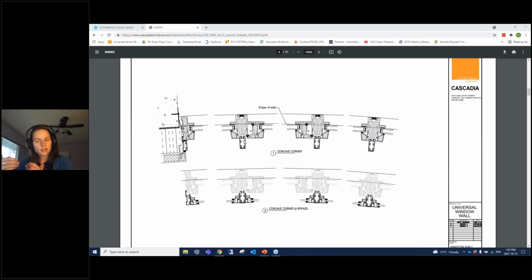There's no thermal bridge there, so to speak. So it's specifically designed to have a negligible impact on the performance. Where performance is impacted is if there's reinforcing in this cavity, which can happen for large windows. There will be either fiberglass or steel in here. And you can see that with modeling that we've done. If you have a performance model that you need to put those details in, we can provide that information.